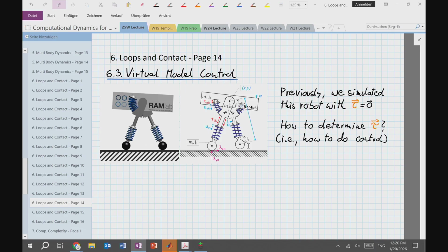So this is why in our exercise, we ended up doing PD control plus feed forward, right? So we get good tracking, but we are also soft in a sense. If something unexpected happens, we have a little bit of give or softness in the robot. And you can imagine if a robot that is controlled this way, the soft way, is put on uneven terrain, then that one leg is going to be a little bit elastic.